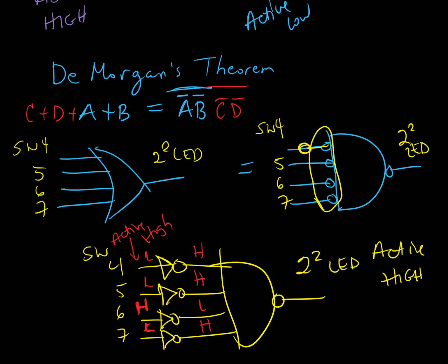And what we see there is we can get away without using these inverters in the lab to avoid having to use extra chips and wiring up extra chips if we go with active low inputs, where all the inputs are high except the one input that we want to be our triggered input in this case, and we set it low to be considered active.